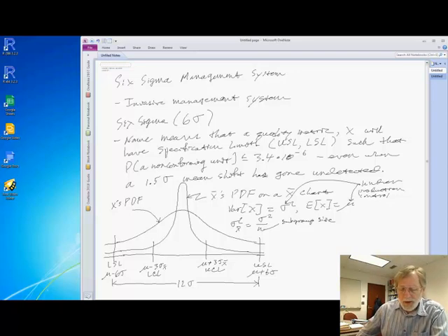And Six Sigma's comment is, if you want to be able to say that you're Six Sigma conforming, a Six Sigma conforming process, if you want to tout that on your website or mention that to potential customers, hoping that you will be a favored supplier to some big outfit that is in a position to buy your unit, then you need to drive the variance down and get the mean in the right place so that it takes 12 production line process standard deviations to span the range between the lower and the upper spec limit, which you have no control over.